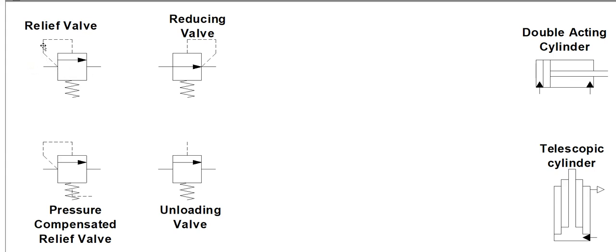If the pressure in this little pilot line builds up enough to push this arrow against the spring, whatever the spring is set at, say 1000 psi, once the pressure in this pilot line reaches 1000 psi, it can move this arrow down, allowing oil to flow through the relief valve, likely back to tank. So it's normally closed, and we are sensing the inlet of the valve.